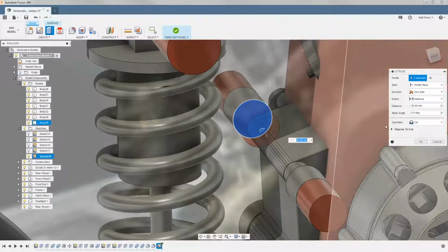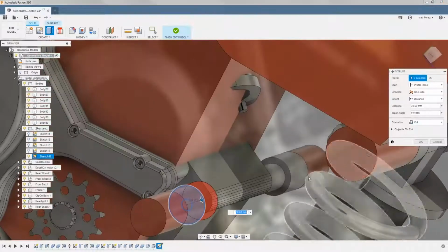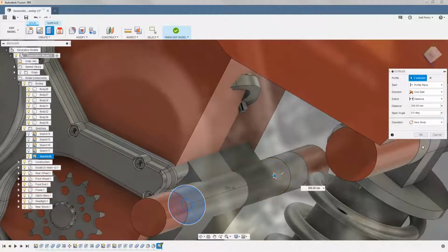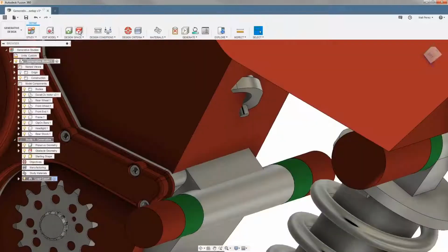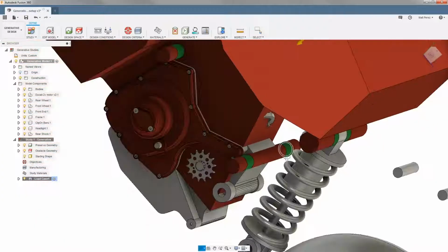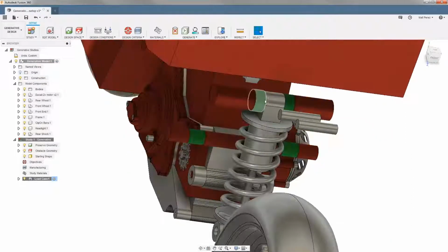And we want to take this entire geometry up to the back edge of this boss, and we'll create it as a new body. So that way when we come back out here, we can go back to our obstacle geometry and add it. And that way a frame won't be created in between there. It'll keep those spaces clean.